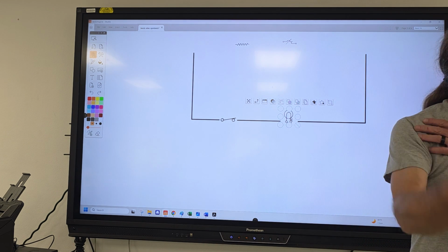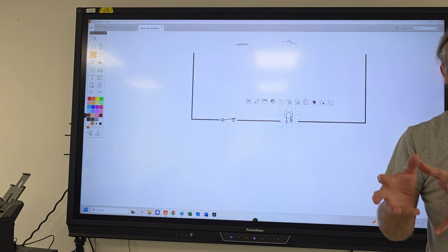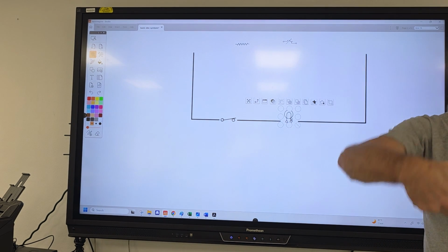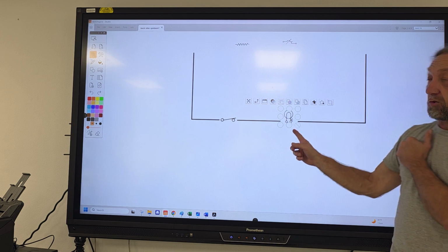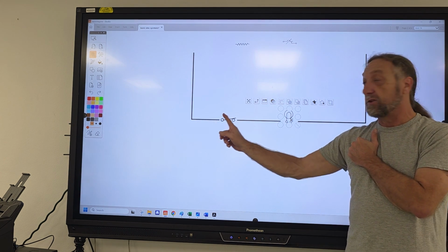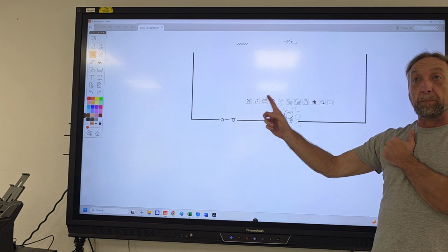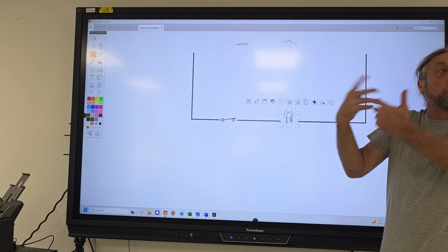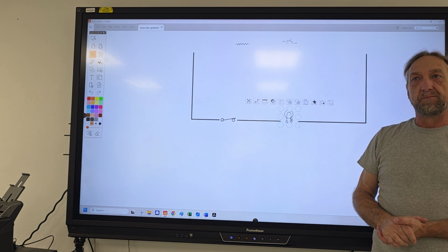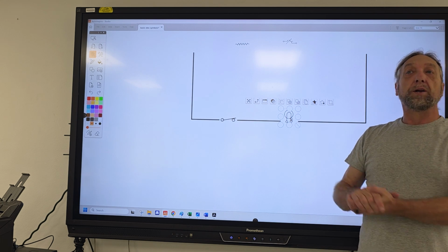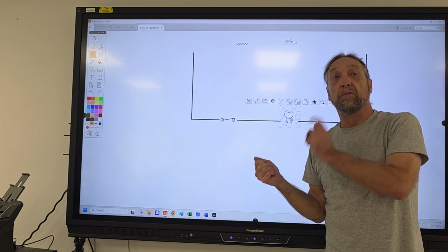Okay? You guys, when you're working on a machine, have to know: washer doesn't drain, it could be a drain pump or it could be anything that tells the drain pump to work. Now I want to look at the diagram and see how the drain pump gets power and all the switches that are controlling it, because if the pump's good, that switch could be bad. Those are the things I need to check when I'm troubleshooting. So when you read the pump, you read the pump in ohms? What did I just say a minute ago? Every load needs what? Voltage.